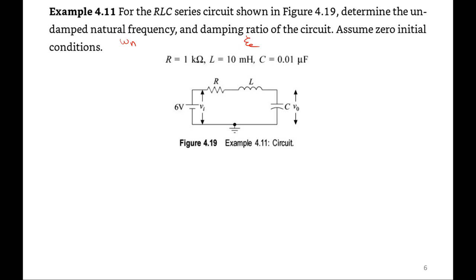Okay, what we will do, we will convert this to Laplace domain, the Laplace electrical network, right? So R as it is, then L is replaced by SL. You know it, right? Already we know this. It is SL in Laplace domain, right? SL, and here it is 1 by SC. C is replaced by 1 by SC. You know it, right?